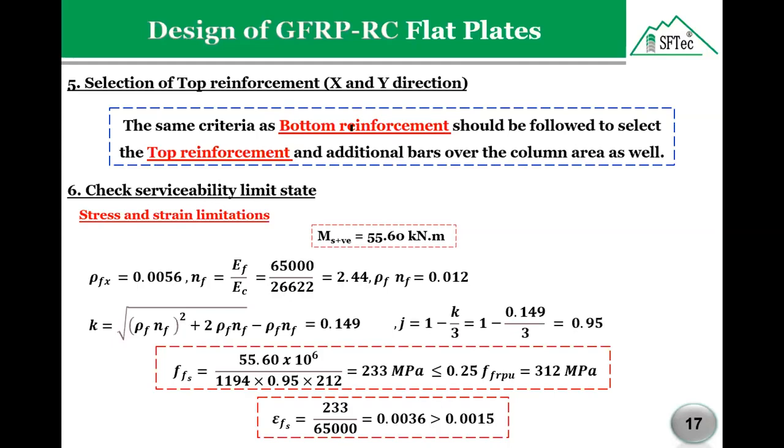Sometimes when you design this kind of slab, there is no need to add additional reinforcement for the top and the bottom. But you know, it's rare to add additional bottom reinforcement, while it's normal to add additional top reinforcement. In many cases that I did before, I already faced a lot of cases of adding additional top reinforcement.